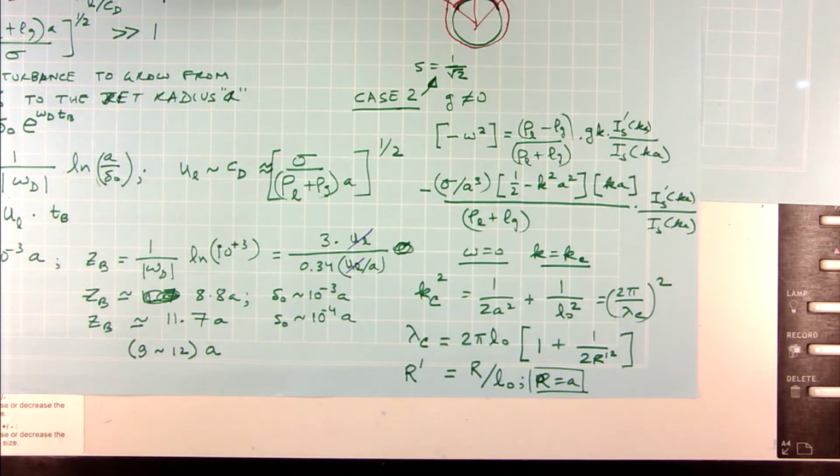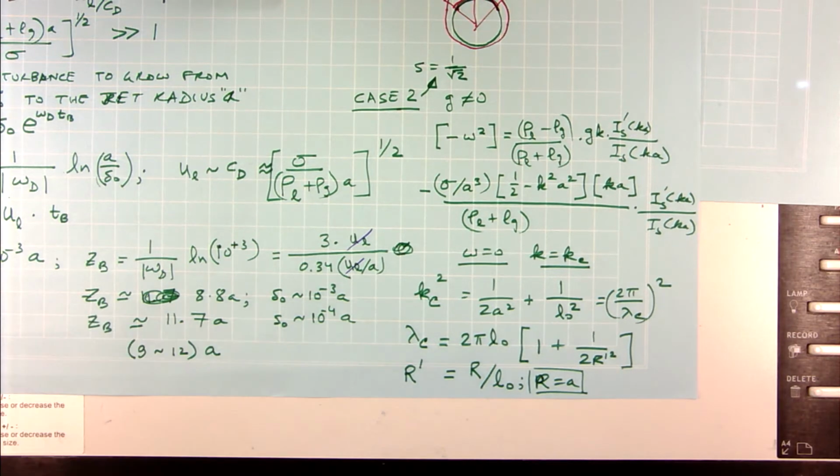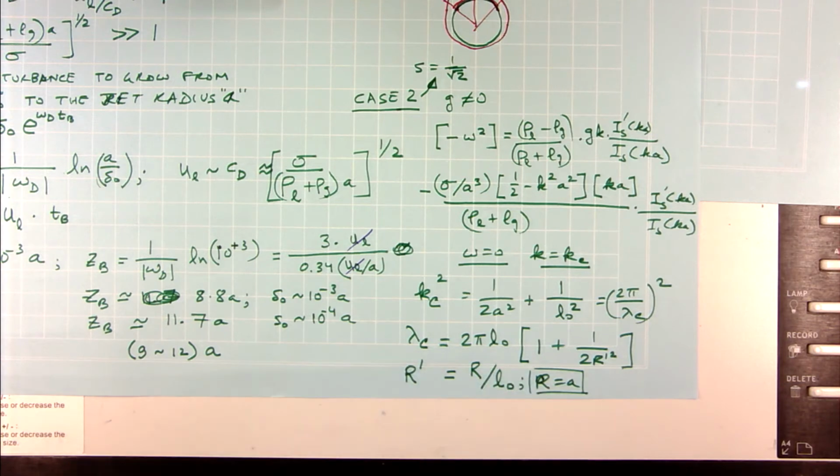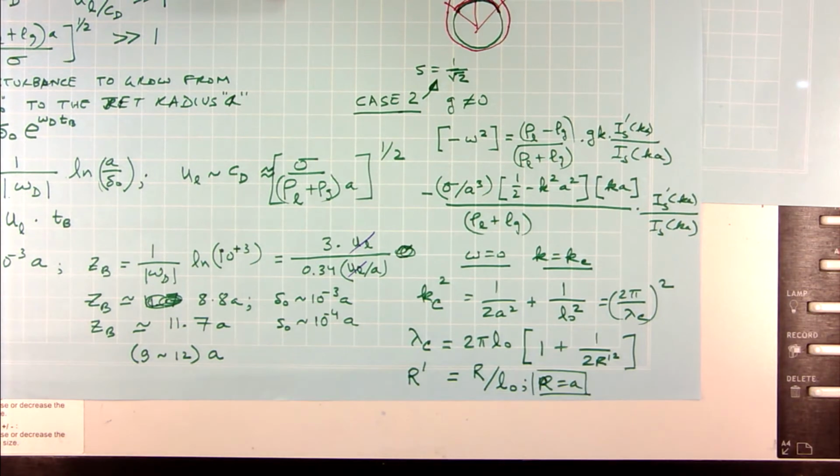Now, there is a particular reason why I wanted you all to look at this equation. Remember I said the diameter of the size of the heater affects your heat flux in boiling. So, if you look at it philosophically, this tells you that you got to worry about the size of your heater. Okay, why so? If it is a very large cylinder, then my 1 by r prime square goes to 0, isn't it?